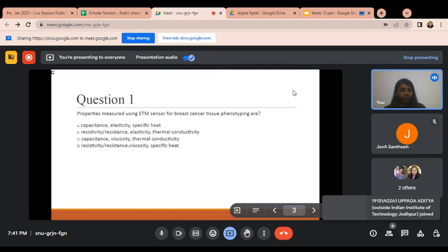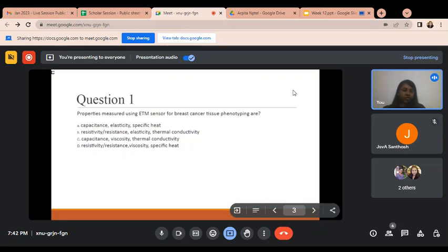Now what do you want? From the photoresist to the deposited layer, it will transfer. So how will it transfer? We will follow the etching process. Like if the underlying layer or the deposited layer is chromium or gold, like the gold, so we will etch by the gold etchant. So we will dip the wafer into this etchant solution, and then